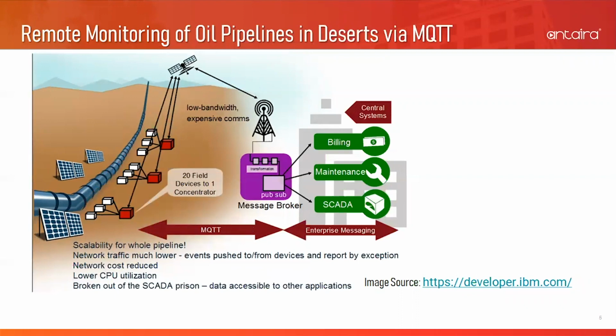MQTT stands for MQ Telemetry Transport, which is an application layer protocol that runs on top of TCP. MQTT was designed for connections between devices with limited resources and was created way back in 1999. MQTT is based on a publish-subscribe framework, which is event-driven and enables messages to be pushed by MQTT clients. An event can be considered as any significant change in state or sensor outputs.